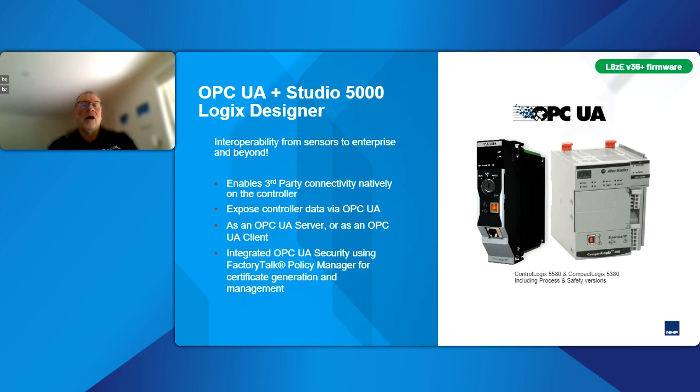For a small system, I'll just say off the sideline here, all good. But for a large system, at the moment, Ethernet IP is recommended over OPC UA. So don't move everything you've got over to OPC UA today. At the moment, the current implementation lets you set the port up as either a client or a server. It can't be both today. Next version it will. At the same time, the next version will be client and server simultaneously.